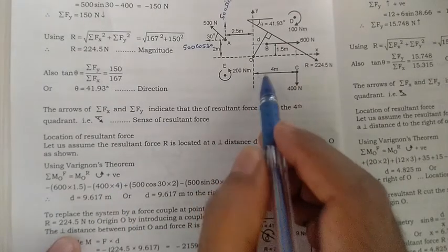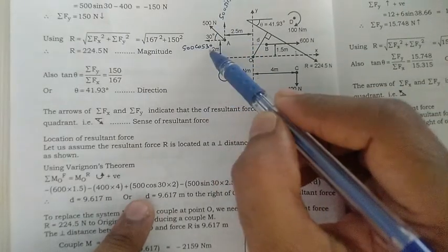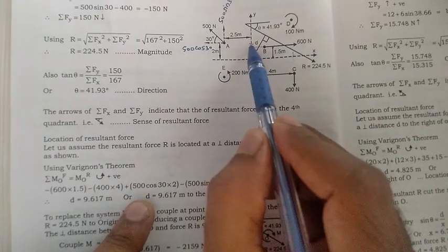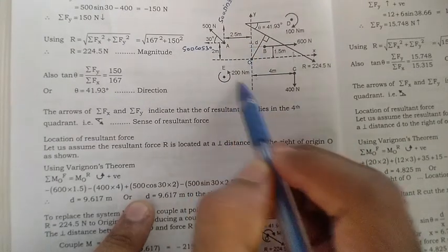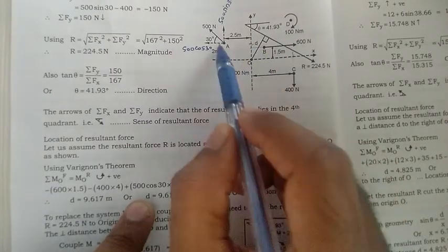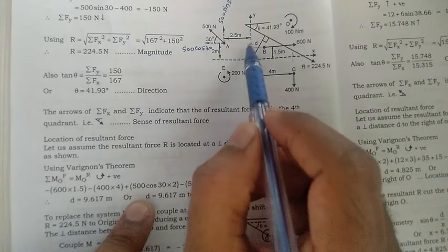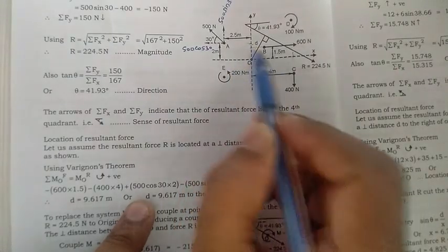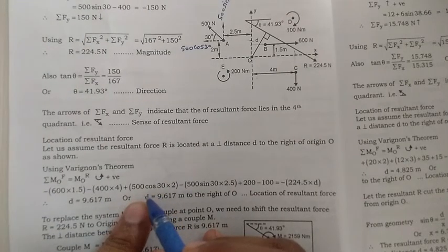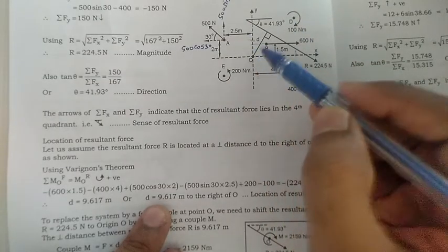Okay. Now next one, 500 sin 30. You have to extend the line of action of this force up to here. And just see the tendency of this force to turn about this point. In which direction? This turns about this point in anti-clockwise direction. So for anti-clockwise direction, give the plus sign for this one. So force multiplied by distance. So how much is the distance? Here it is 2 meter.